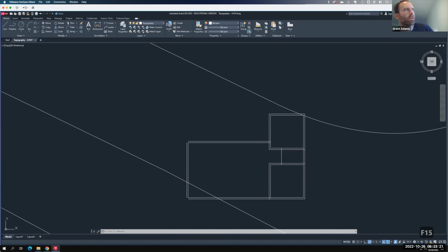I mean, yes, absolutely. Walls have different thicknesses. Interior walls, if you wanted to do them at 4 inches, that would be fine. What's actually interesting about walls is depending on how you create a wall, what it's made up of, the thickness is never actually 6 inches. And a lot of times in architecture, we just generically call it 6 inches and say, hey, that's fine.